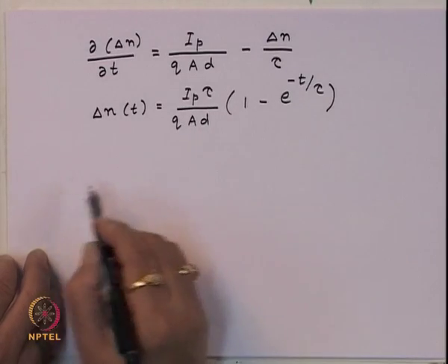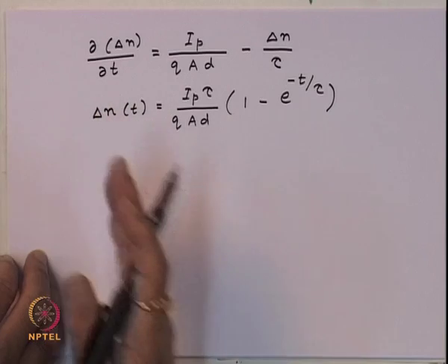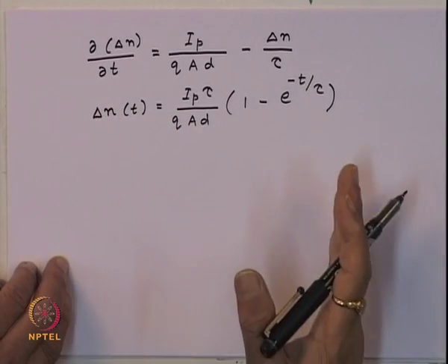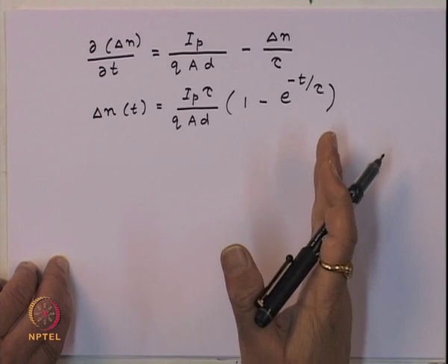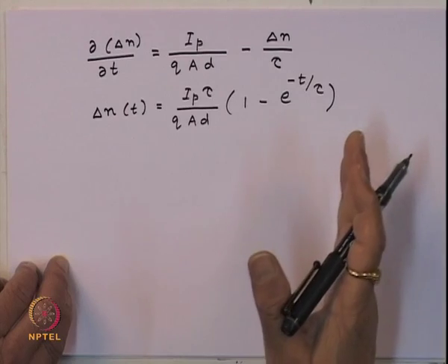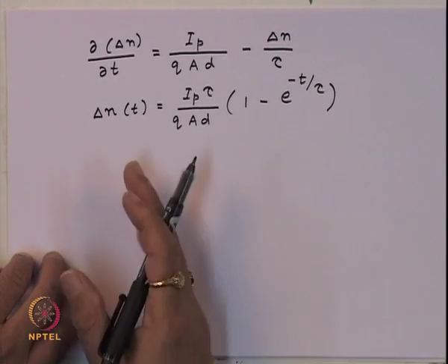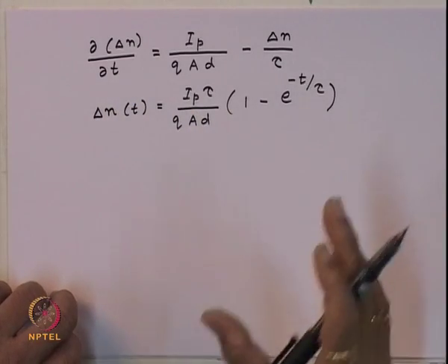Now, if you look at the laser characteristic, we know that if the laser was unbiased, the initial current is 0, and then for lasing to take place, the electron density has to increase to a certain value where population inversion takes place, and then the laser will start lasing. So, it is going to take a certain time to build the electron density in the recombination region to a minimum required value.